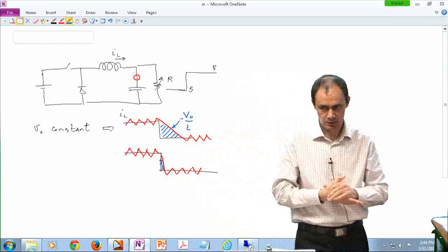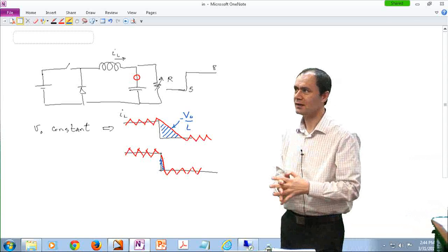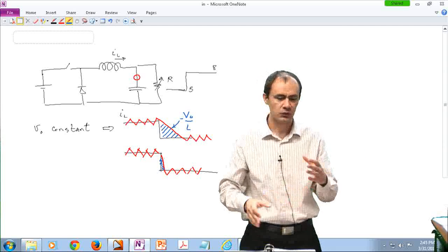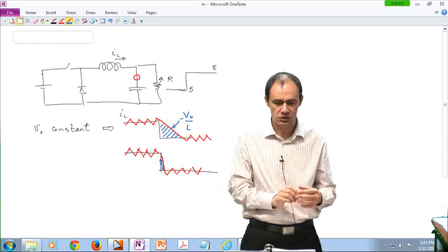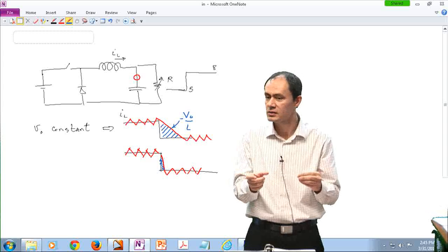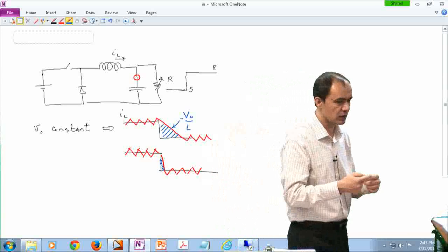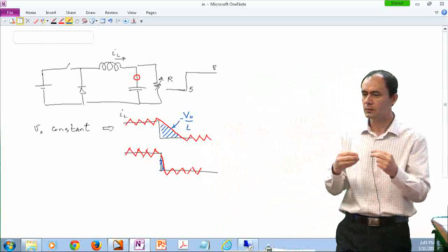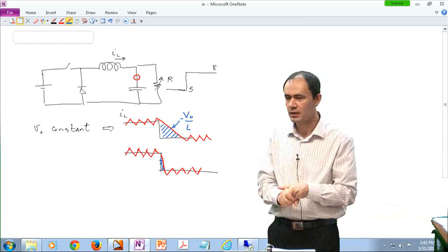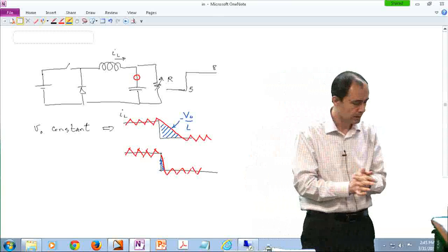Yes? How do you manipulate the value of the inductor? Excellent question. Practically, it's very difficult. In low power applications, you can. For instance, your winding could have a core that moves a little bit, so you can make it smaller or larger. You can have some sort of mutual inductance and manipulate with that. At chip level, it's possible. At larger levels, it's very complicated.